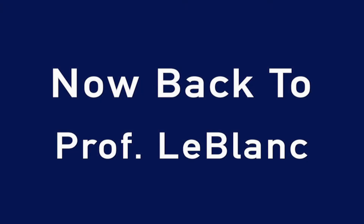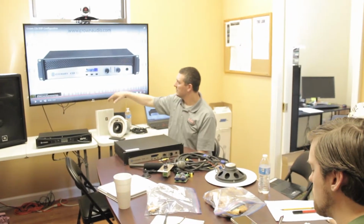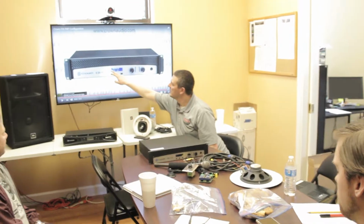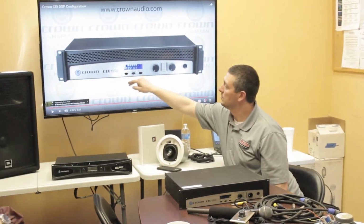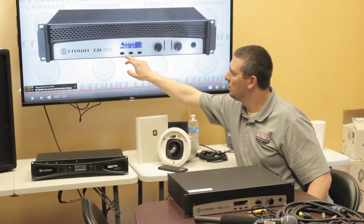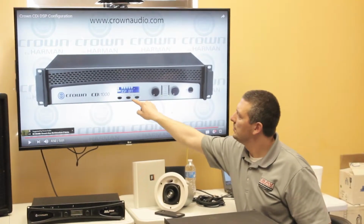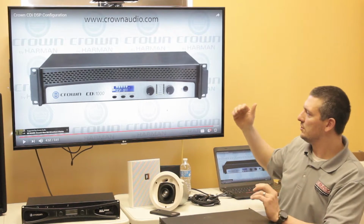Alright, so from this front panel, you've got your select enter, you've got a previous, and you've got a next button. So up in the left-hand corner, you've got channel 1, channel 2, and then it'll show which mode you're in, preset mode or configuration mode. To enter configuration mode, you have to hold down select enter, then hit up, and then select enter again, and you'll switch from preset mode to configuration mode.